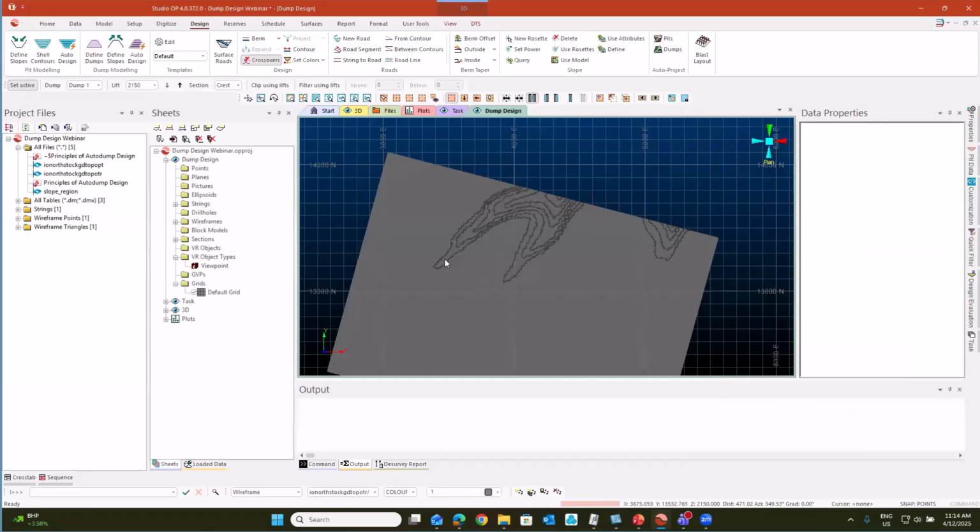So we also want to maximize the topography to essentially get some extra area in which we can infill a dump. So I'm just going to say I would like a new string file, and I am just going to generate the base constraint string for this particular dump.